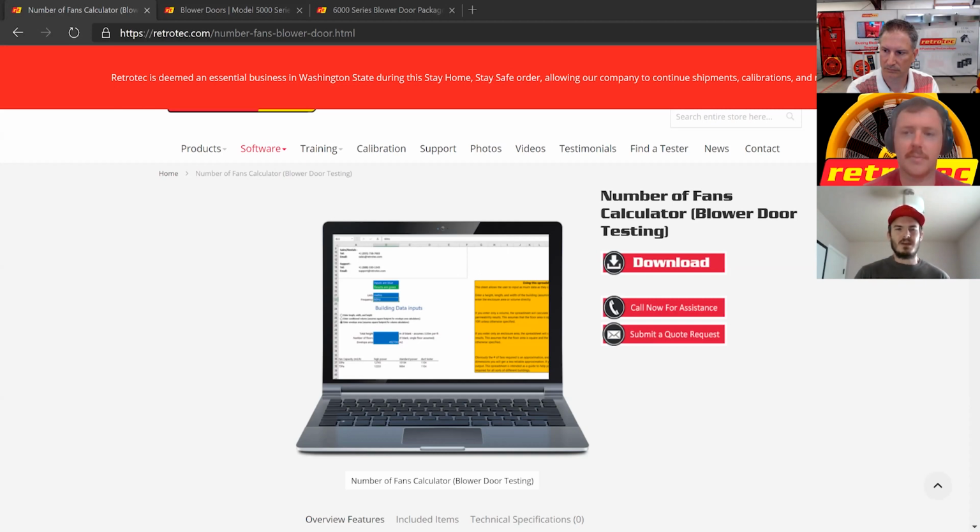Basically, it's just square footage multiplied by the average height of the conditioned volume, whether it's the eave, the top of the attic, or the actual ceiling, and then you multiply that by your air change rate cutoff. So your volume times your air change rate gives you your max allowed flow in CFH, and then you can divide that by 60 to get your CFM.